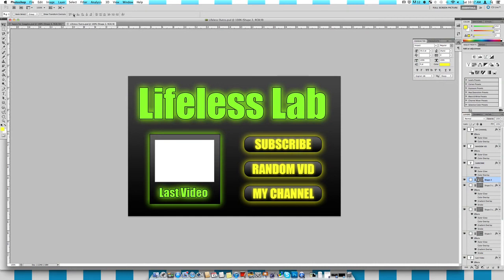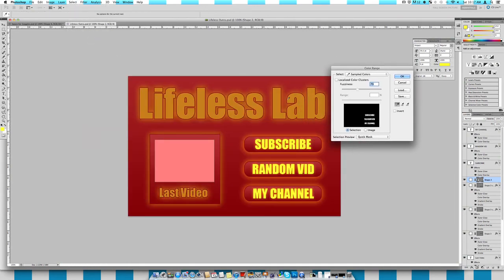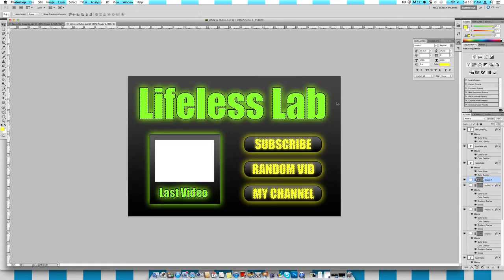And the last few things I'm going to show you are in the select menu. So really the only thing you want to look at is color range. So this is another selection tool really. What you can do is just click on any color. If you want to select another color as well, you can click on another, and then those colors will be selected. You can change the range of colors that will be selected with this fuzziness slider, and then you press OK and they'll be selected.